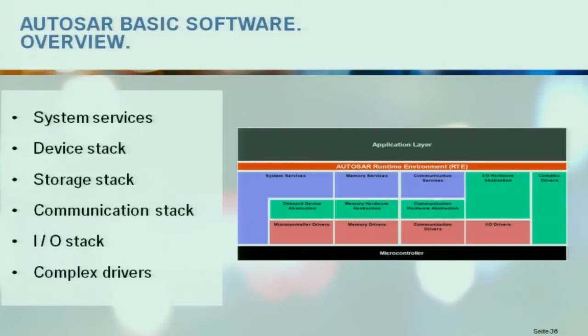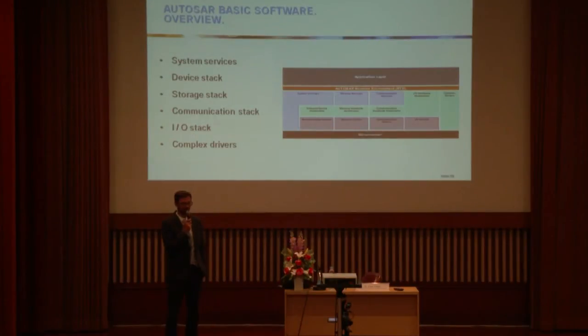If you need very fast software functionality, then you can use complex device drivers, for example, for combustion engines. They have timing requirements on a microsecond level. This is one use case. The other use case for complex device drivers, if you have old software, which is legacy code, meaning legacy code which is not AUTOSAR compliant, and you want to reuse it, then put it into a complex device driver and it can be used in an AUTOSAR environment.